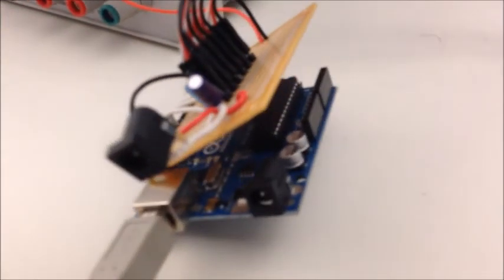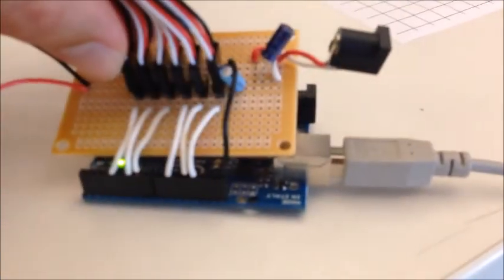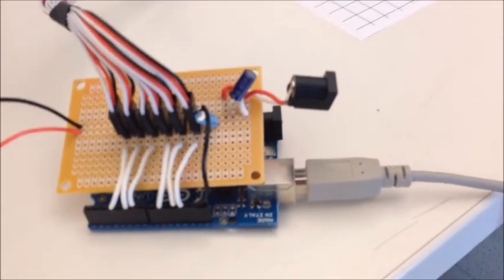Also noteworthy is how we're controlling the robot. We've got USB providing a serial link from MATLAB, and then there's a microcontroller, which is in this case an Arduino Uno, and that provides the pulse width modulation for the servos and reads from the serial port. And then here we have each of our servos in order from the base here to the most distal joint, and they're just receiving standard pulse widths, and only moving to where MATLAB tells it to move.